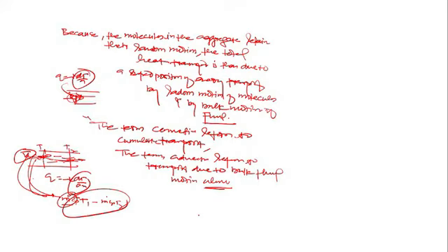Are you getting the point? Here energy is m dot Cp T. M dot is what? Density into cross-sectional area into velocity, into Cp at T1. This is the energy entering here. This is due to bulk velocity, due to advection only. Is this clear? This is energy transfer due to advection.